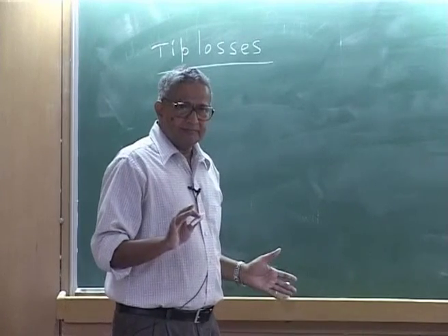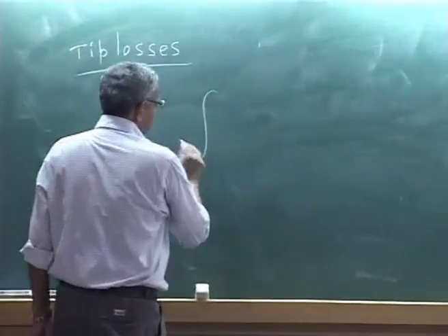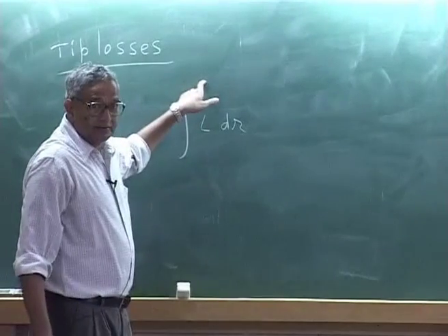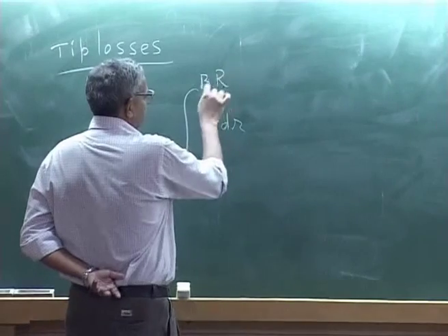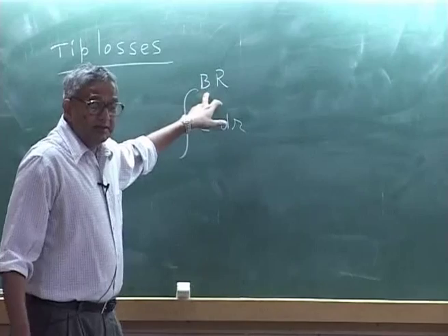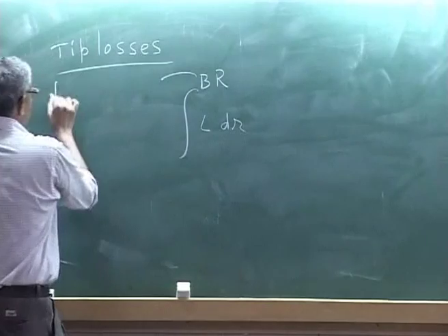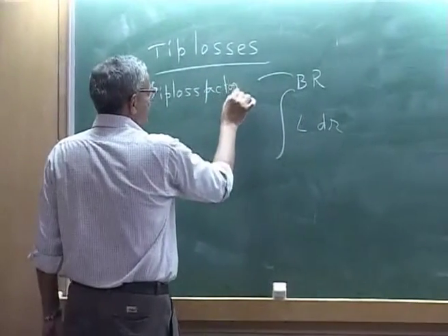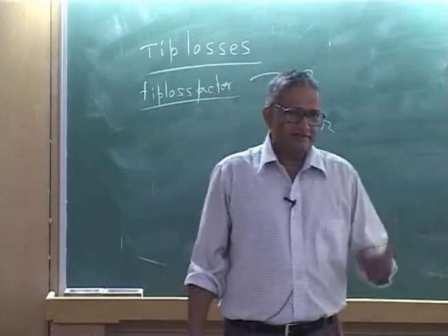What the final conclusion of that is, instead of integrating that lift dr from 0 to 1, do not go to 1, you go to B. 1 is actually non-dimensional. B is a tip loss factor, and it is less than 1.